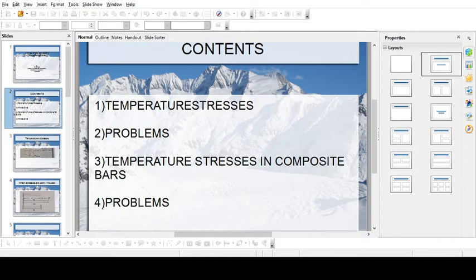Next, the stress induced if the ends yield by 2 mm. We know that strain is alpha t minus delta by L, where delta is the yield. So stress will be simply alpha t minus delta by L into E. E value is 2 into 10 to the power of 5 into, 12 into 10 to the power of minus 6 into 80 minus 2 by 8000.